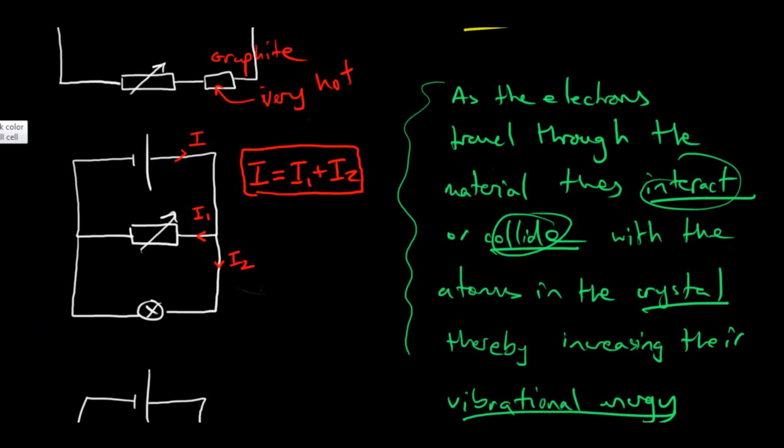So what we did was we connected a voltmeter here, and we connected a voltmeter here, right? And to check if this thing with the currents was true, you just need to put an ammeter here, and put an ammeter there, and put an ammeter here, for example, and then you're measuring the current through this branch, and you're measuring the current through that branch, and you're checking if they add up to this branch, which they should. So that's with the ammeters.